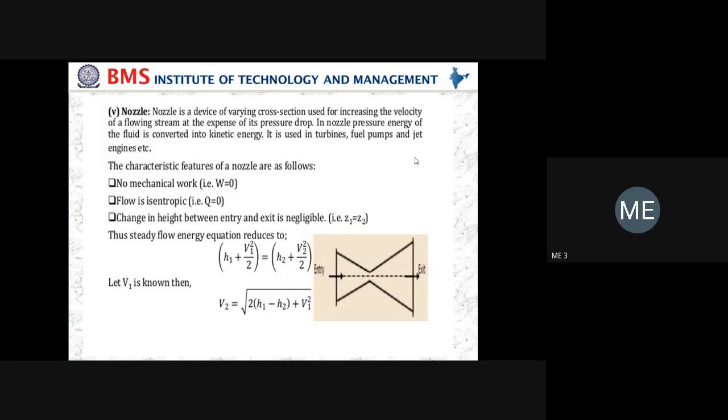Similarly, the change in internal energy. You are learning this in the third module and fifth module. The change in internal energy is given by mCv into delta T, where m is the mass of gas, Cv is the specific heat at constant volume, and delta T is the temperature change. I'm telling again and again because in all the problems they ask you to find out work done, heat transfer, change in internal energy, change in enthalpy, change in entropy. These are the 5 parameters you should remember.